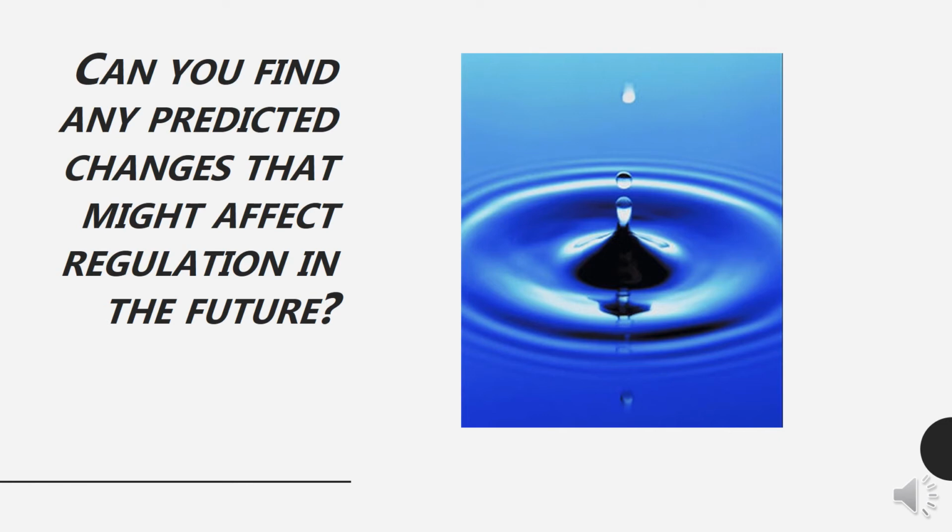The U.S. EPA has added bromide and total organic carbon, another important precursor to disinfection byproduct formation, to the Safe Drinking Water Act as of 2016. This means that the EPA has required drinking water utilities to monitor bromide and total organic carbon to establish occurrence data that can be used to consider future regulation. The U.S. EPA has also included several haloacetic acid groups containing brominated species in this new regulation.